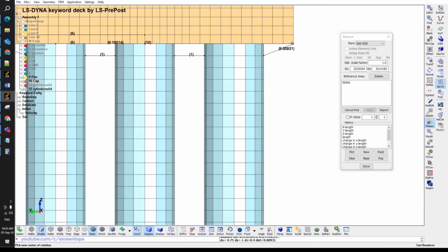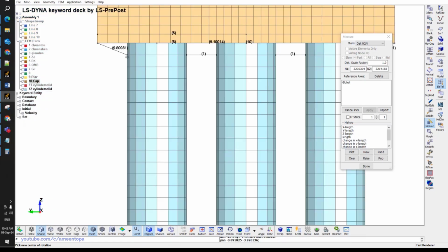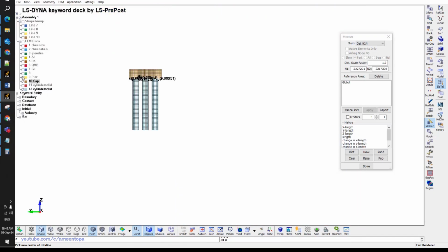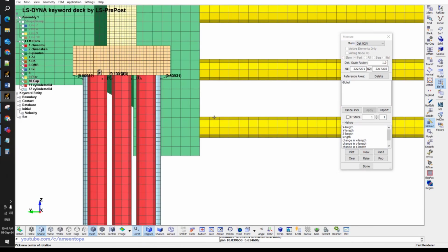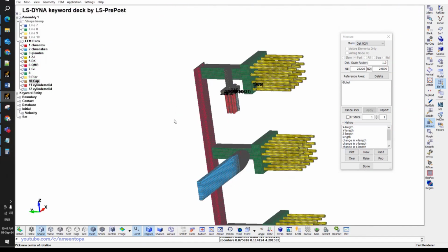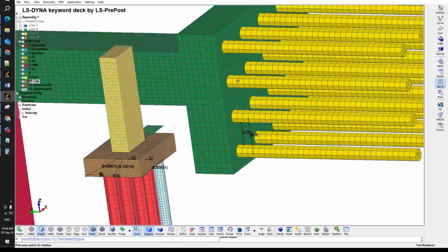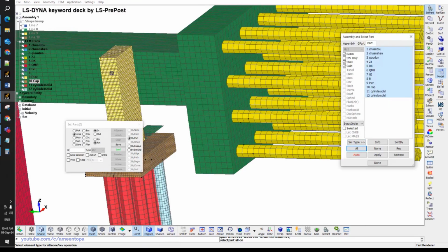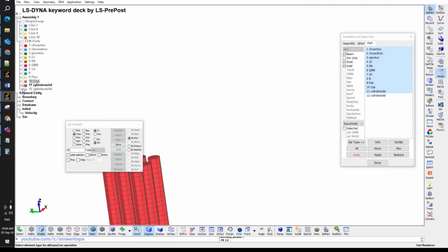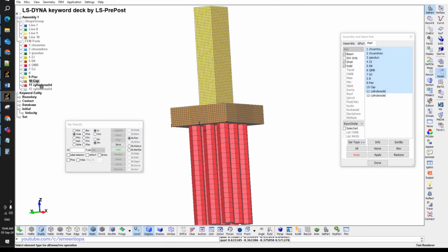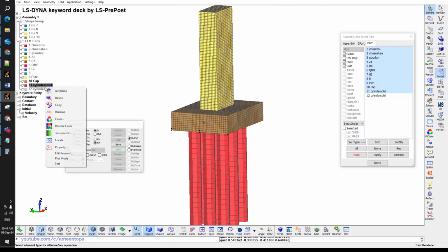So in the old model, the spacing between pile caps is about how much? 2 meters. In the old model, it's more than 2 meters. You can see if we consider the diameter, it's 3.75. If from center to center, it's 5.9. So it's completely bigger, because the pile cap is also bigger. That's my point: it's not meaningful to compare with the old model because the old model is very large in size.